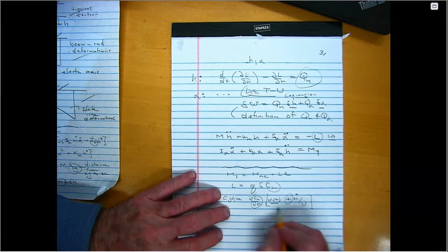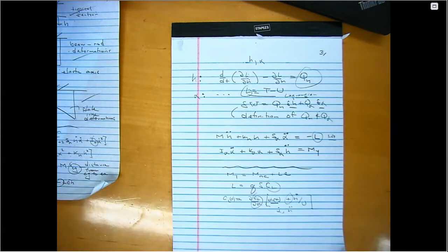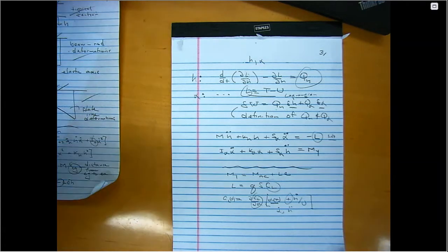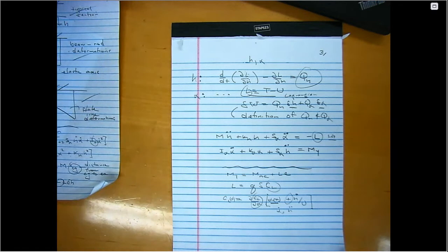But then you could also have other terms. You could have alpha dot terms. You can have H double dot terms. By the way, you can't have an H term. Why not? Well, think about it. I'm in the wind tunnel with the wing, and I have certain aerodynamic forces on it. I move it up 10 feet. But if the flow is uniform, the absolute value of H doesn't change anything aerodynamically. So the lowest time-driven effect of H is always H dot.